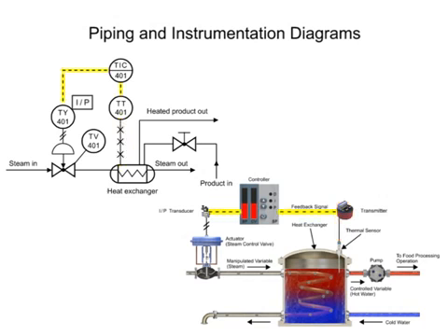A dashed line between components indicates an electrical signal. The controller and indicator is the instrument where the transmitter sends an electrical signal and is shown in the functional identifier at the second and third letters, I and C. Balloons with a solid dividing line indicate that the instrument is board-mounted. An electronic signal from the controller is indicated by the dashed line.